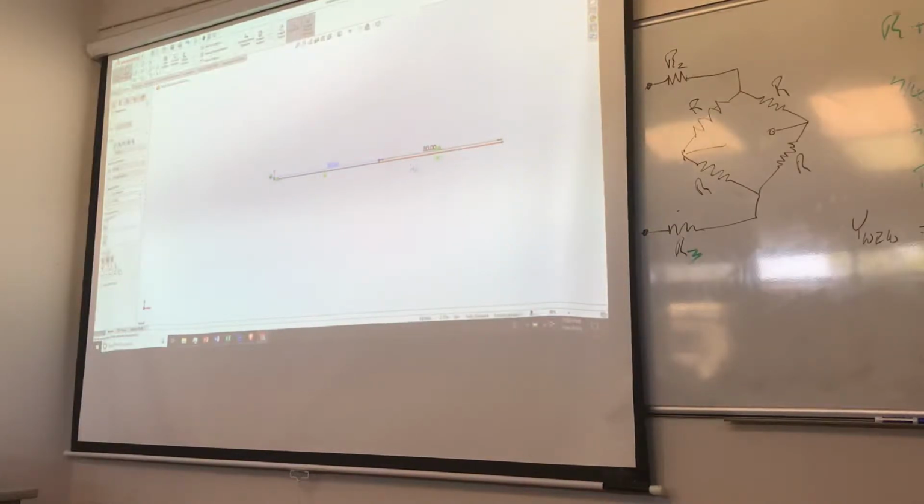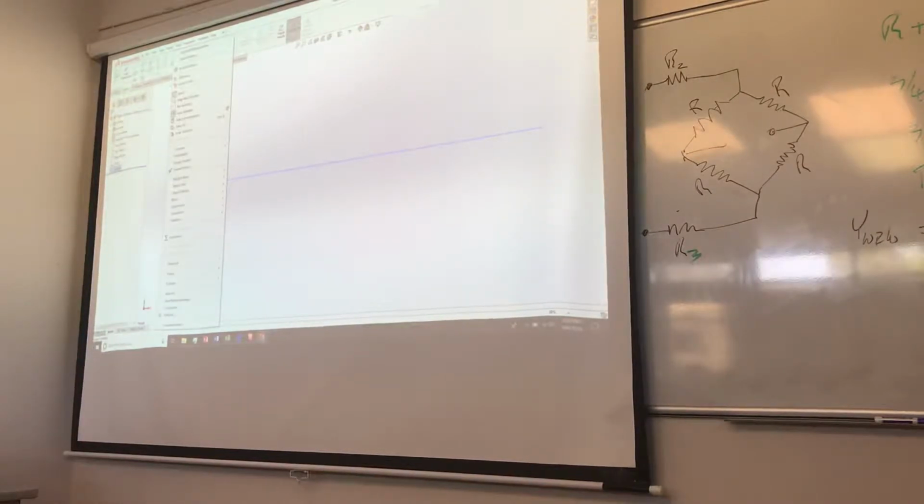Okay, there we go. I can be ornerier than SolidWorks is. I've got 100 inches of beam here, which I'm going to say is close enough. Okay, and I can exit out of the sketch now. And I'm smart on this. I go, okay, I got my axis. I can go insert weldment, structural member.